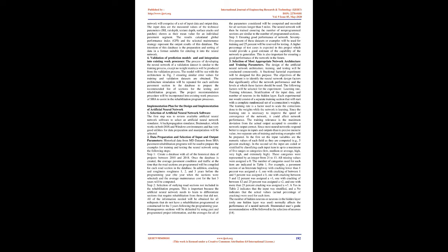While these pavement datasets can facilitate training more sophisticated ML models, systematic data errors can make model training unreliable and lead to incorrect decisions. In this project, data cleaning will be performed in 2 stages, error detection and error repairing. Error detection would identify common errors including duplicates, missing values, integrity constraints violations, typos, mixed formats, and replicated entries.